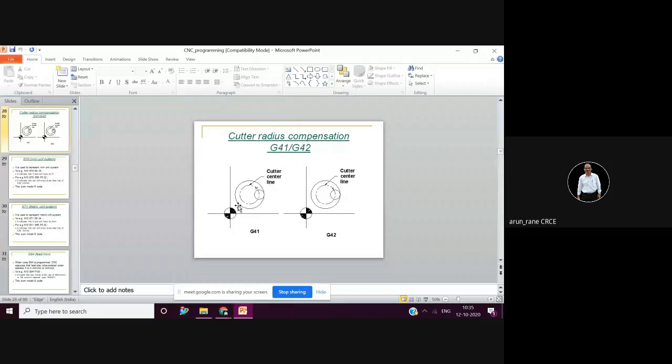Or if it is a rectangle which you have to machine, then what you give in the program is this border. That means only if your cutter diameter is 0 will you get this. But how is it practical? It is not possible, isn't it? How can you machine with a cutter having 0 diameter? The cutter will always have a diameter.